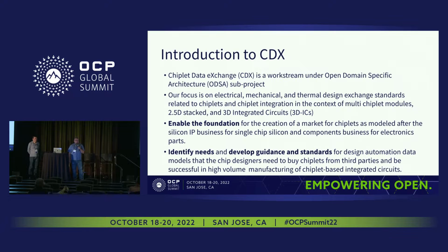And last, I'm going to conclude with a call to action and some concluding remarks. CDX is a work stream under the ODSA sub-project. Our focus is on electrical, mechanical, and thermal exchange standards, and really anything that's related to chiplets and chiplet integration in the context of multi-chiplet modules. This includes both the 2.5D and 3D contexts.